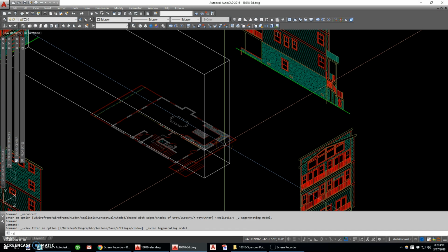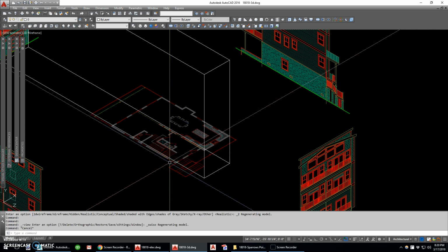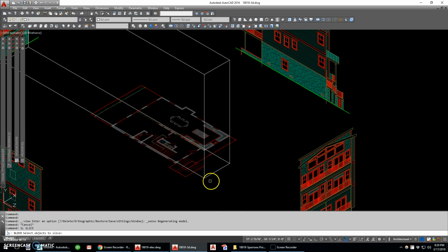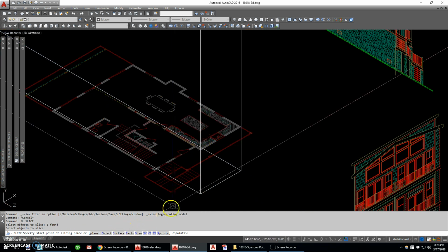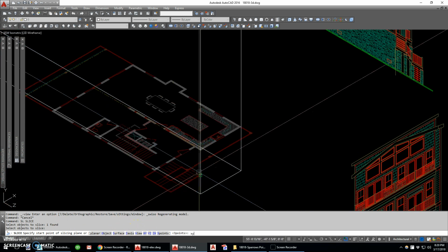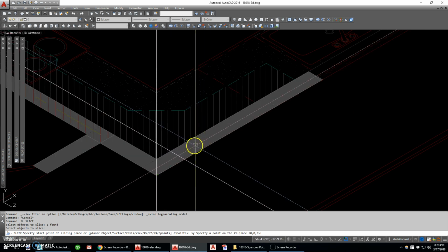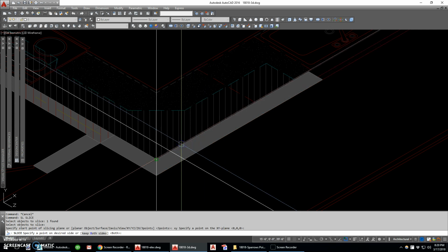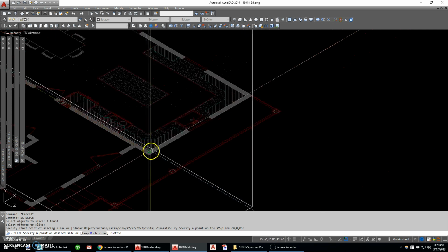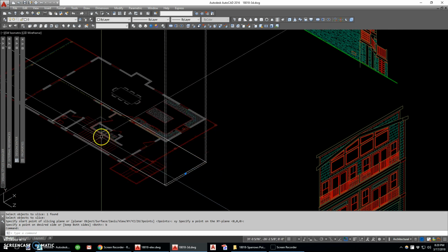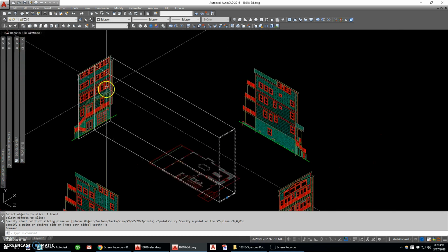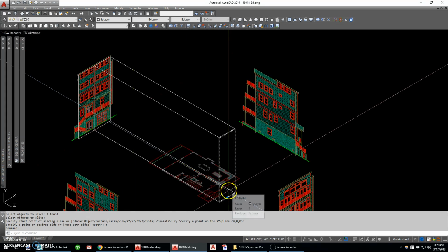What I'm going to do is create the front wall of that house by using the 3D command slice. I have it shortcutted to SL. I want to select the object I'd like to slice, enter with my mouse, select start of slicing plane. So I want to tell it that I'm slicing on the XY plane because my XY is tilted up. I'm going to select the inside of the wall, and I'm going to say B for keep both sides because I don't want to get rid of that other geometry yet. So what that did was slice this solid that we drew with a polyline command, and then extruded, and now we sliced it.